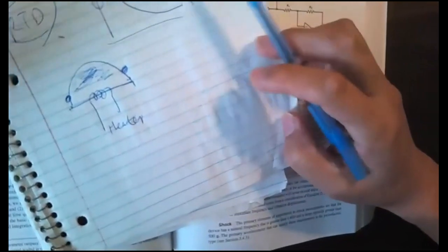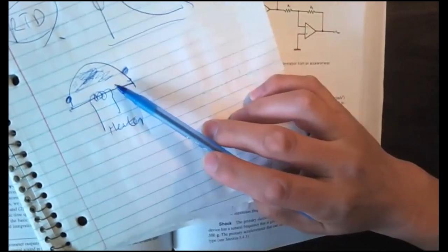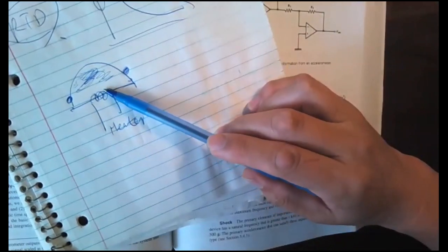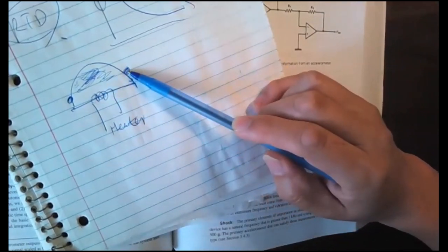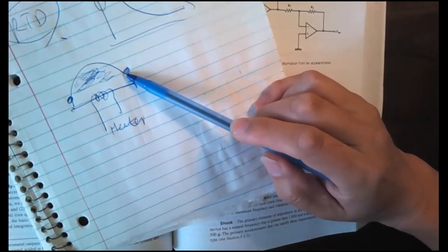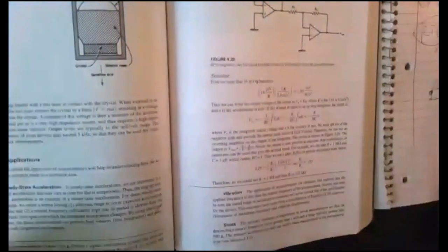So there are many different types. This is 2-dimensional. So it will measure X and Y tilt, tilt in X and tilt in Y angle. It will also measure acceleration by measuring how fast the temperature changes. So acceleration is done by how fast the temperature changes. All right, that's another type.